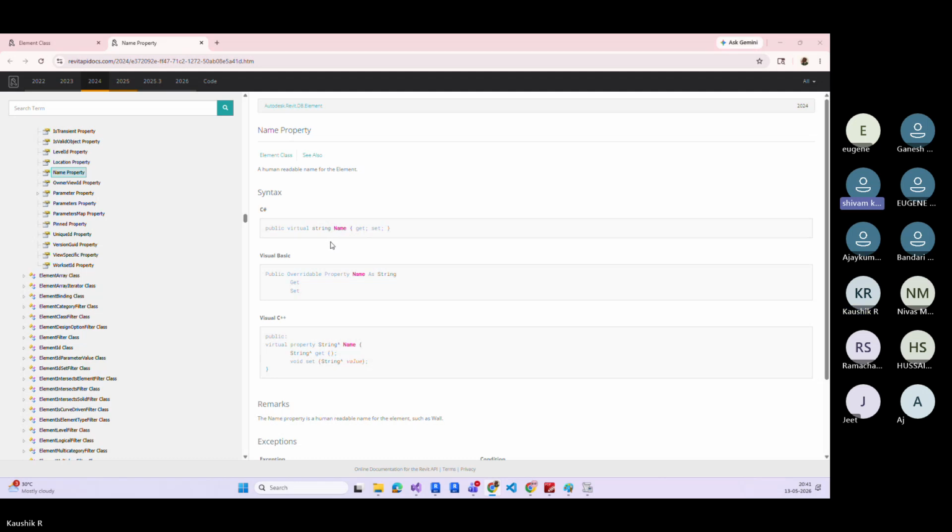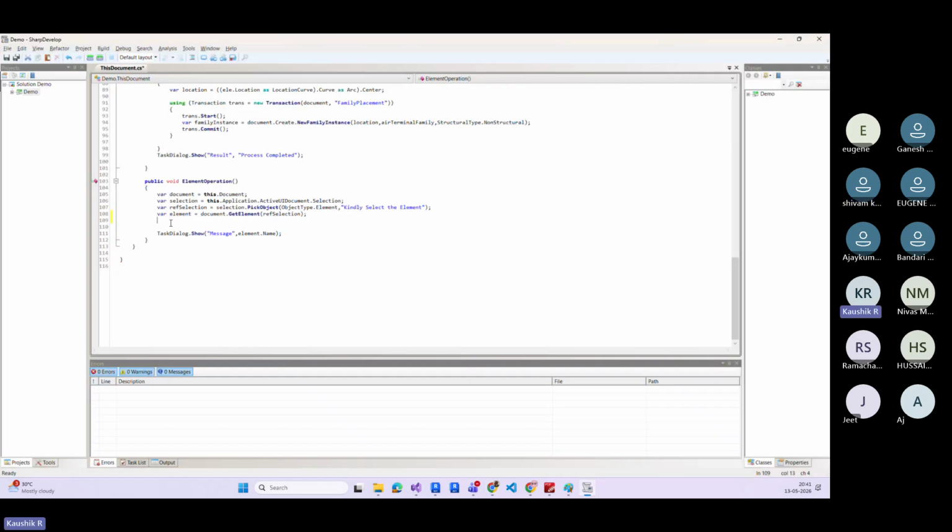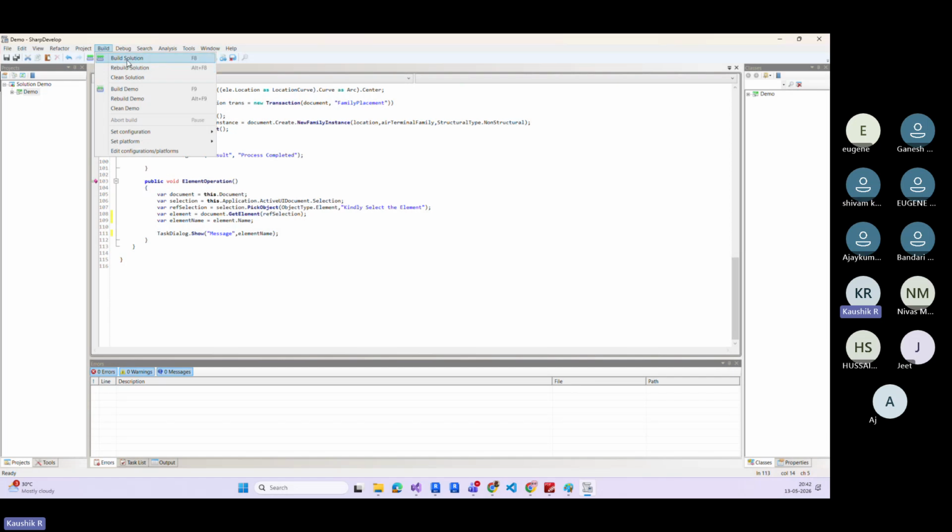Shall we try? Okay, here I'm going to store the result. I'm going to do a certain operation and save that in some RAM. So I'm writing var elementName. Why am I using var? Previously I could use string also, but to make it dynamic, I'm using the var keyword. In live classes we will let you know how it works. Here, in the element object, I'm getting the element, I'm writing element.Name, and I'm putting this element name in the output plus v.